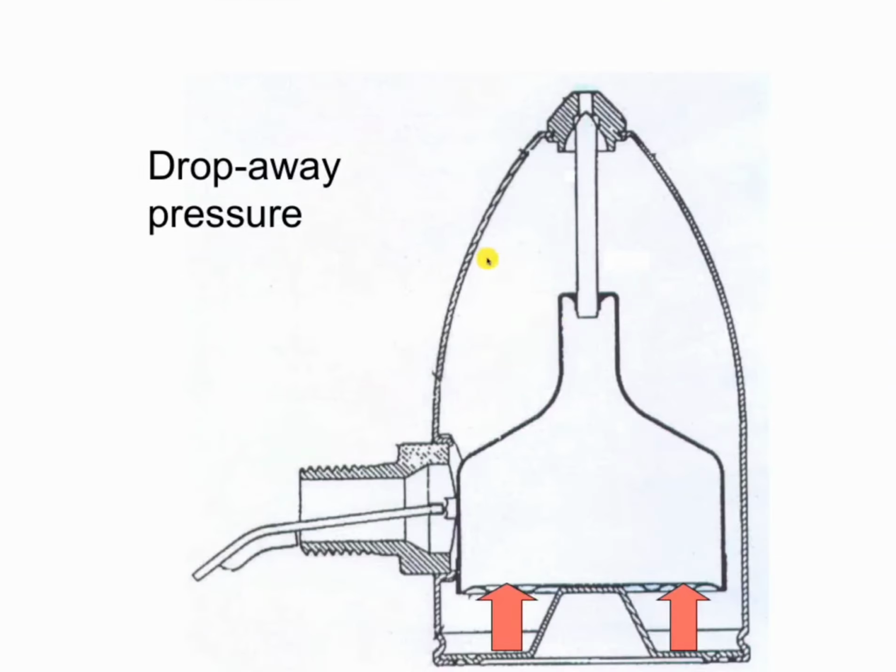"And that is shutting the vent. Now, that's being opposed by atmospheric pressure that's trying to fit in through this little hole. So it's kind of like what makes a car lift in a garage work, right? You got a big surface, big piston, small piston. This is trying to push down. This is pushing up. So when you got steam pressure on here, if it's on there all the time, this is going to keep the vent closed. Stays closed all the time."